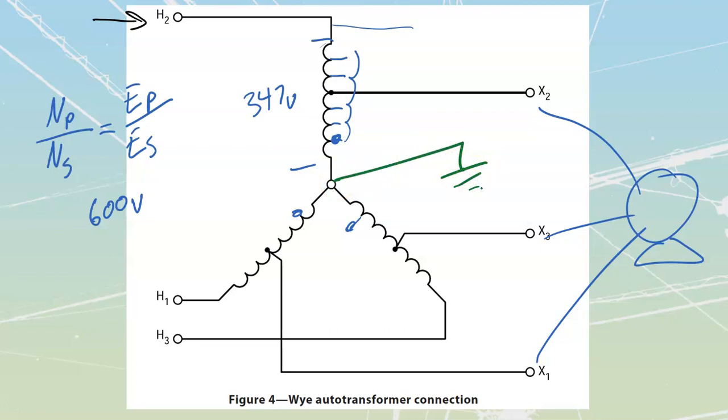If you don't ground the neutrals on these ones, you're going to get problems with your third harmonics. Harmonics are just multiples of our 60 hertz. So a third harmonic is going to be 3 times 60, or a 180 hertz waveform. It gives us a really humpy sort of line that can cause a lot of problems for our voltage, because it has a really fast leading edge, then a slow dropping out edge, and it never properly peaks correctly. So we want to try and avoid that. As soon as we get these harmonic voltages, we also start to lose equipment. It damages the equipment because it cannot withstand that sudden sharp shock.